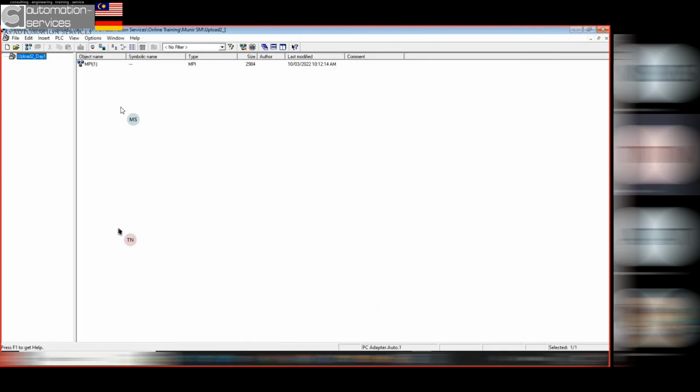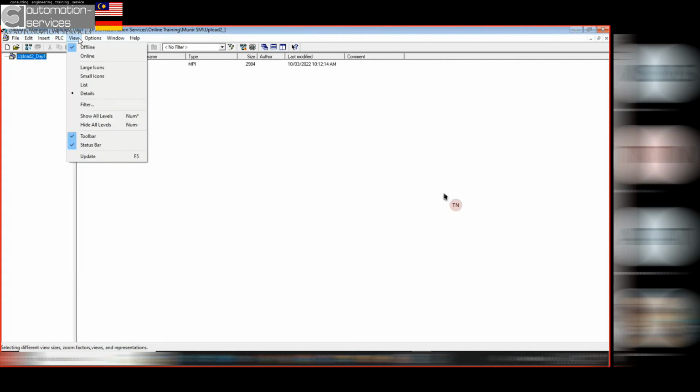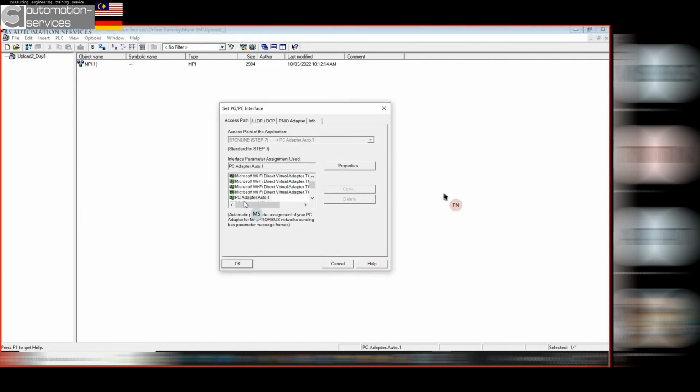Upload day 2. Okay, there's this now. Go to Set PG/PC. Yeah, now can. Why just now cannot? Because the Simatic Manager is in administrator. I opened it as an administrator, that's why. Oh, okay.